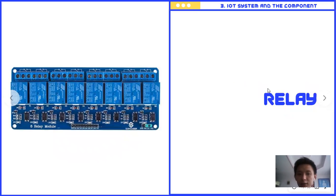And next, this is the relay. Actually, this relay will work best as a switch. So actually, this relay is used to imitate the real control panel of the jet engine 7.1. Like we know that on the control panel there are switch and push button. So if the control panel is in the form of a switch, then we will use one relay, and if the control panel is a push button, then we will use two relays.